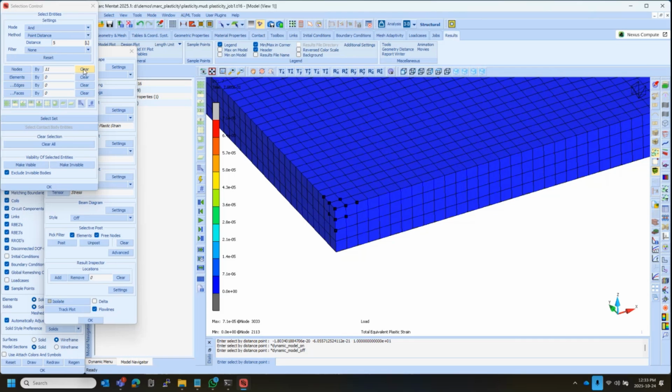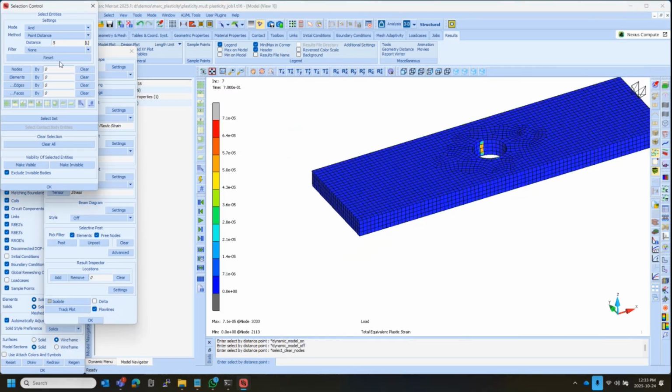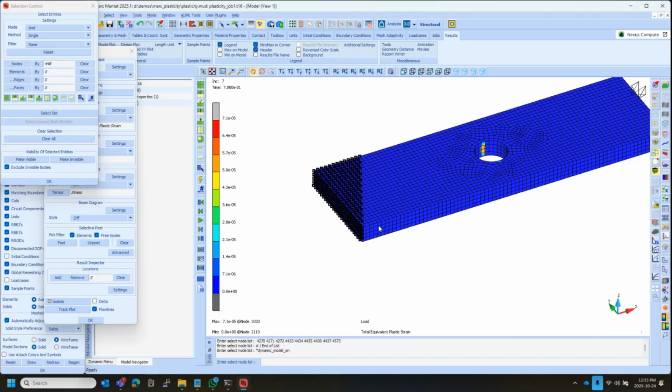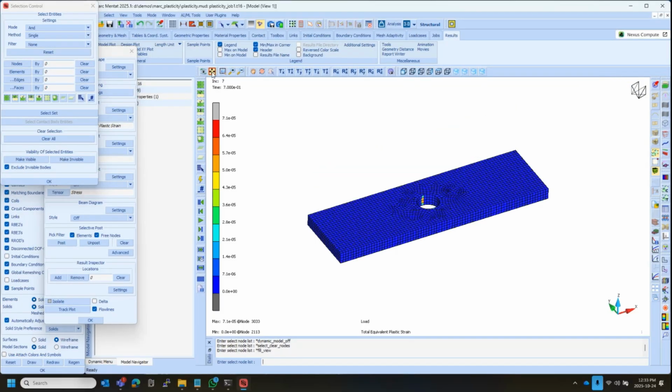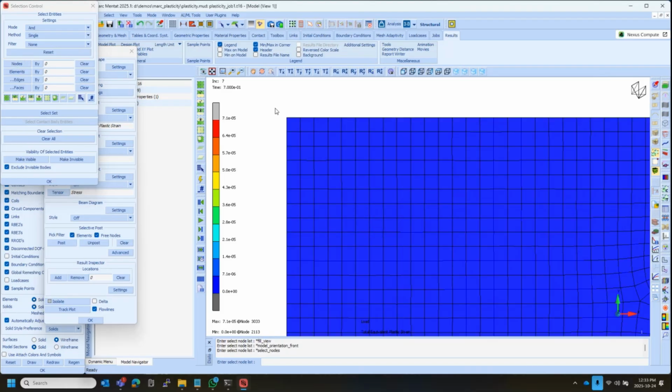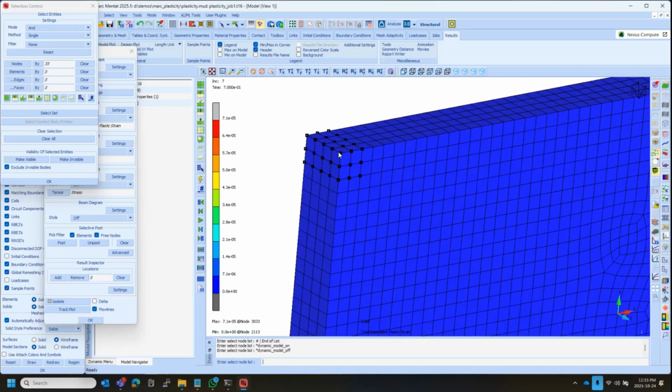Yes. Okay, so I wouldn't be surprised. The reason he asked is probably this. If I'm not careful, I do this: I select nodes, and it only picks the nodes on the face. So just to show that, if I plot it from there and I select nodes over there, 1, 2, 3, 4, 5, and that is 9 times 5, so it's 45.